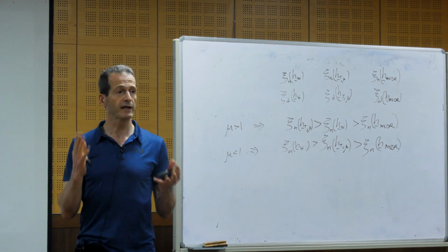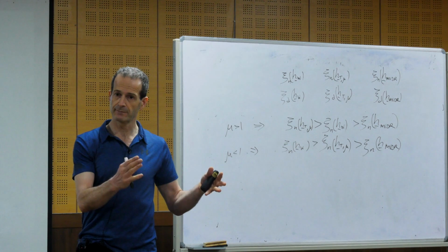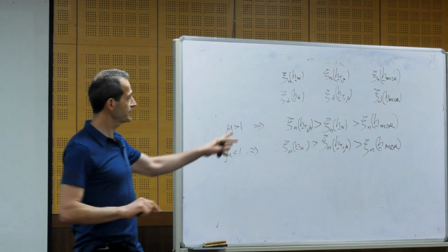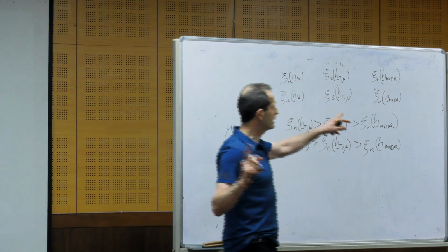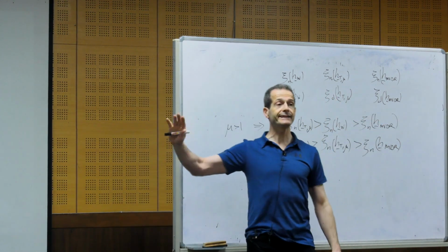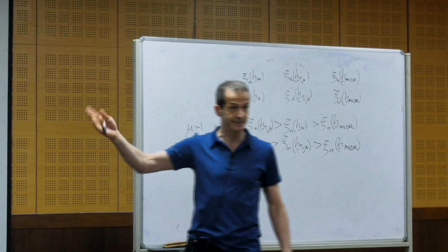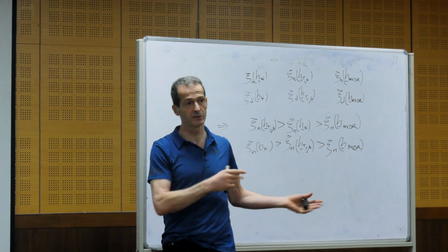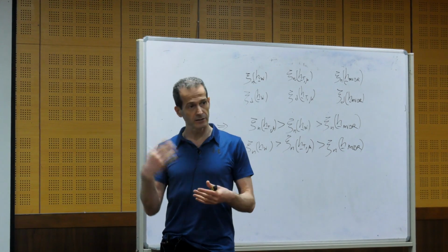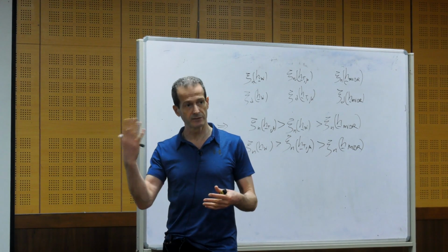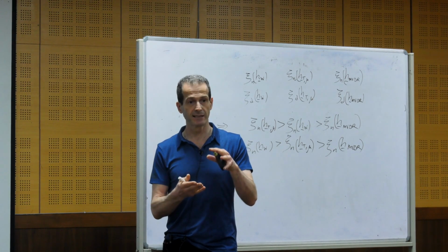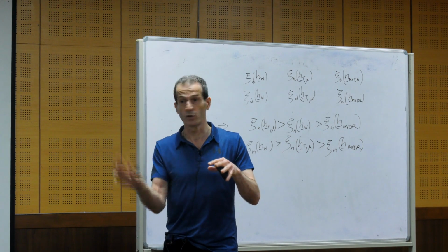And then we want to find what is the signal subspace, what is the noise subspace. The MVDR will remove only the noise in the noise-only subspace, while the other filters, the Wiener for example, will remove the noise in the noise subspace, but also distort the signal to achieve more noise reduction.